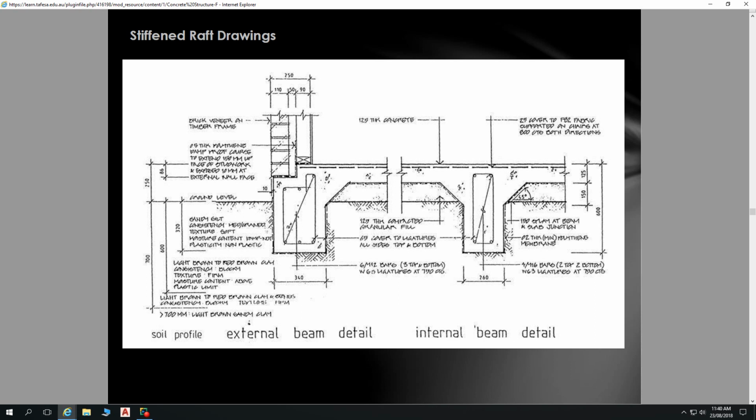Are slump and MPa related together? They are. A major driver of your concrete strength, so your MPa, your megapascals, is the cement to water ratio. Certainly the ratio of your large aggregates and small aggregates, and their qualities, play a part as well. But one of the major factors is your cement to water ratio.